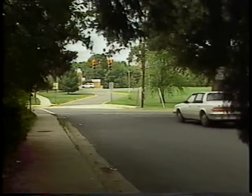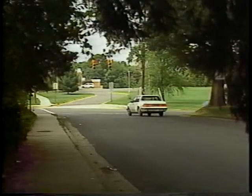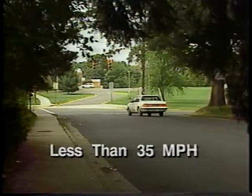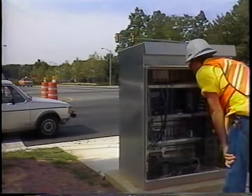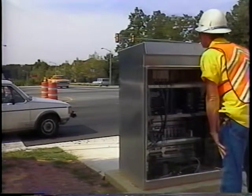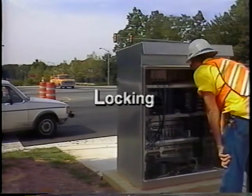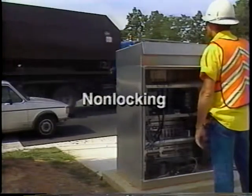In addition to phase timing, you must consider the speed of the oncoming vehicles. Approaches of less than 35 miles per hour are considered low-speed approaches. Approaches of over 35 miles per hour are referred to as high-speed approaches. And the detector design for a given approach of any speed depends on whether the controller phase memory has been set for locking or memory on detection versus non-locking or memory off detection.